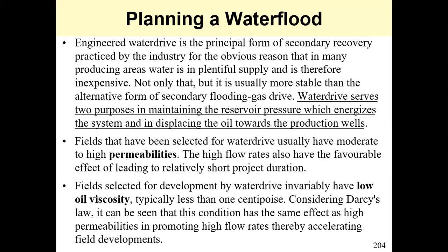Considering Darcy's law, it can be seen that this condition has the same effect as high permeability. You know that your flow velocity is directly proportional to permeability and the inverse of viscosity. So the whole idea is that moderate to high permeabilities and low viscosities would enable you to attain high flow rates. Thus, you can recover more in less time. And of course, that is important considering the time value of money.